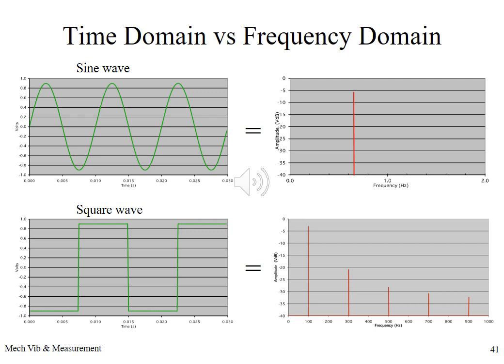In this slide you can see the difference between the time and the frequency domain for various different signal types. For a sine wave, where we have a periodic oscillation between the amplitude plus and minus with a frequency that leads to a period in time which is 1 over the frequency, the frequency domain equivalent of that signal, which is determined by implementing a fast Fourier transform typically in digital signal processing, is simply a single peak at the frequency with an amplitude that is equivalent to the amplitude of the peak of the sine wave.